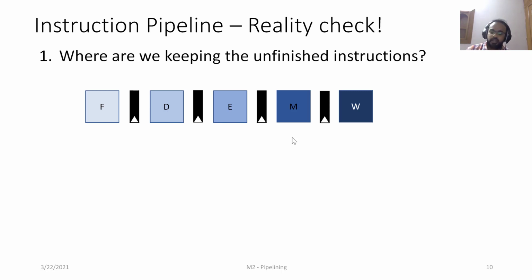In one cycle, the inputs to these buffers would be driven by the previous stages, and in the very next cycle it would be driving as input to the next stage. In this way we can stabilize the data flow between different stages of the pipeline. So it's all good, right? We solve the problem, but what is the side effect? Nothing comes for free, right?